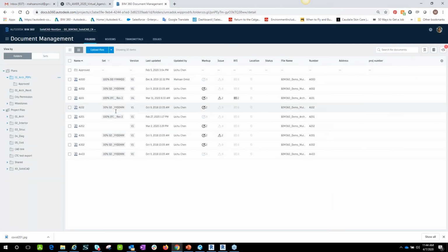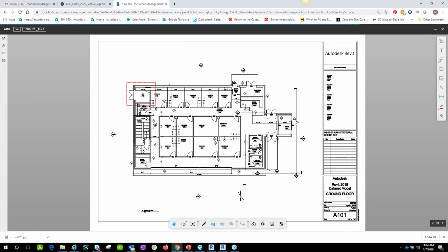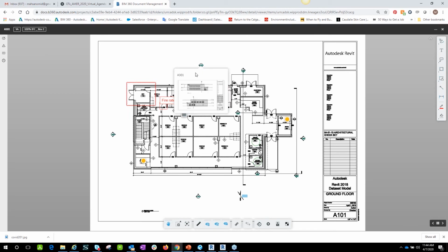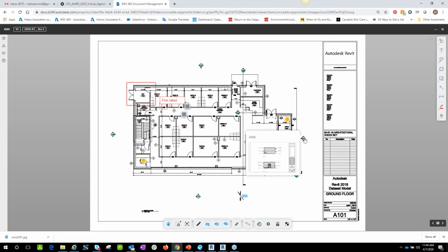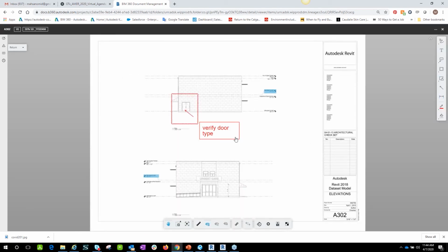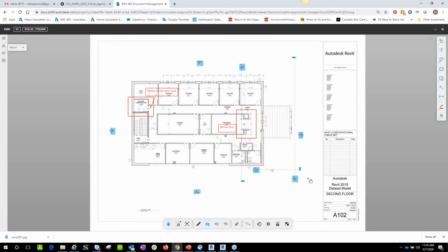As I go through each of these sheets, it's highlighting all of those sheet models that are supposed to have the hyperlinking in them. Clicking on them automatically takes me to the specific sheet. Also, inside of your elevation, if you're hyperlinking your floor plans, similar to what is going on in Revit, right-clicking on that takes you to that floor plan.